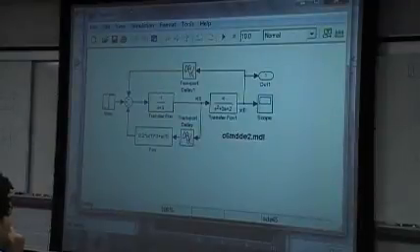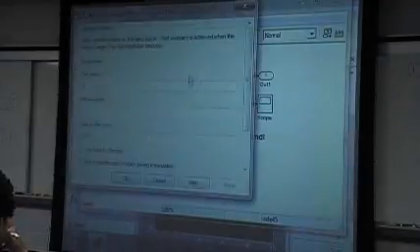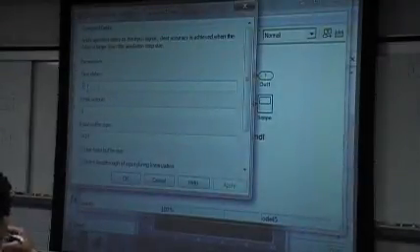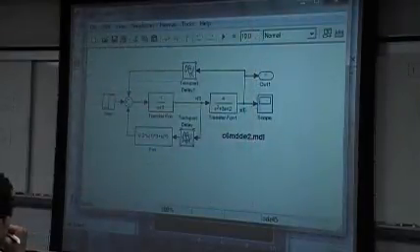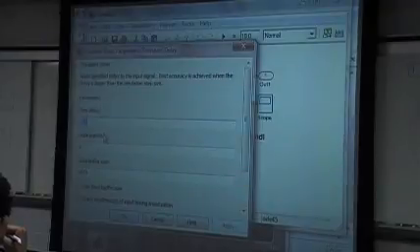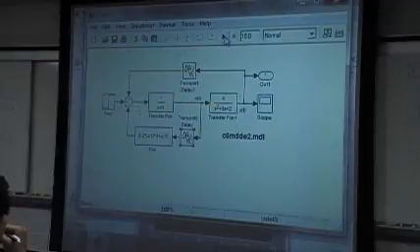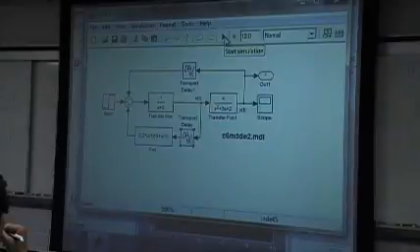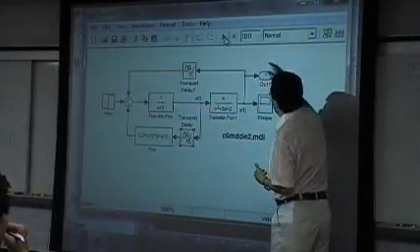And you have to set the delay constant. For instance, for this one, this is y. Double click it, and you will see that the delay constant there is 1. And for this one, we have to put 0.5 as the delay constant. In this way, we can easily model the delay differential equation. And we can click the icon. Since we use two output blocks, one is the output, the other one is the scope.